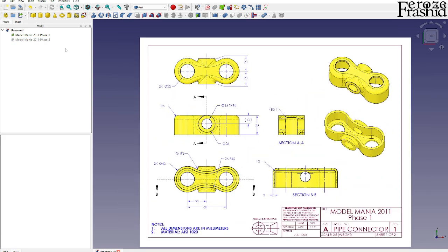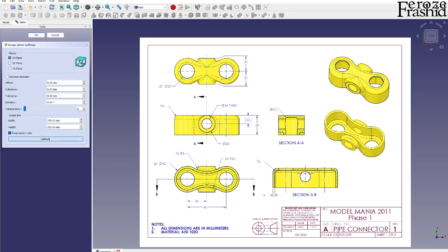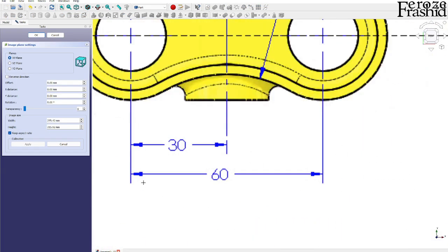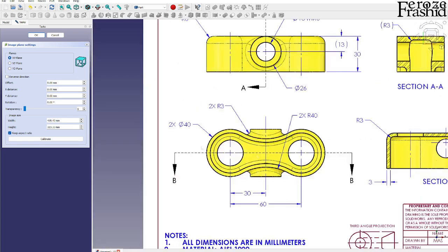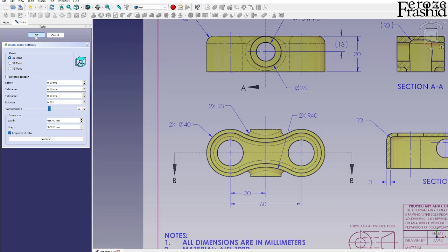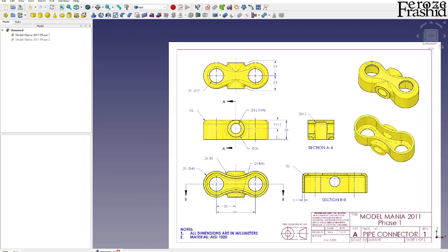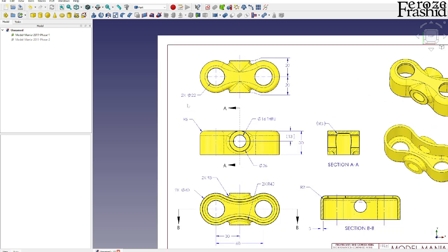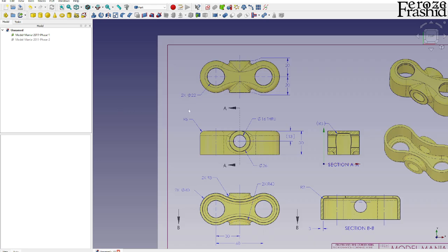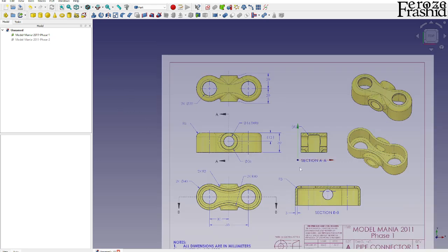All right, let's go ahead and start working on the image processing. I'll take this length as my calibration length. And it's also good to make it half transparent. Okay, and this model I want to start from the top, so this will be the figure I'll be using. And let's go ahead and bring in the axis cross by pressing AC on the keyboard.